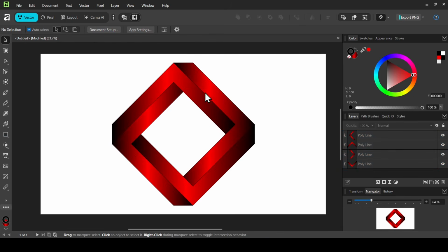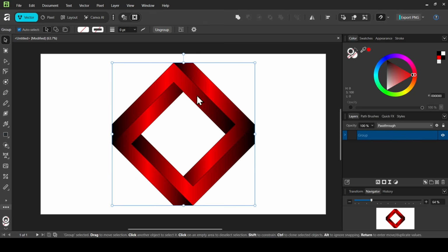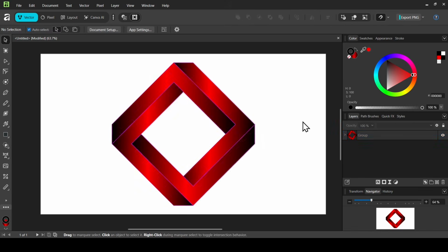Now if you want to remove the outline here, I'm going to select everything, click on Group to group all the layers. I'm going to left click here, so here you can increase or decrease the outline. And then there are small gaps here. I'm just going to fill them. So click on the Contour tool. And then I'm going to double click on the radius. I'm going to add the 0.3 radius and then press enter. And then I'm just going to select here. So here it is.